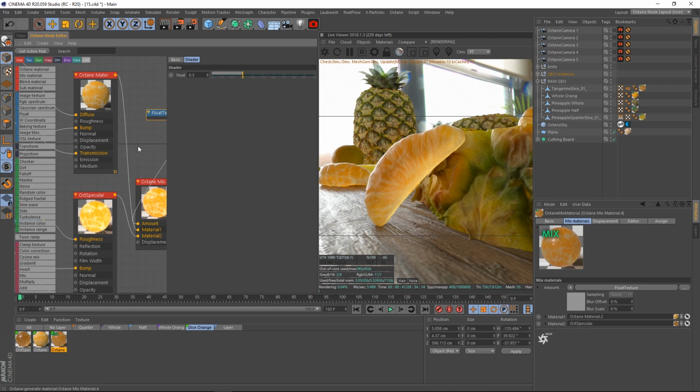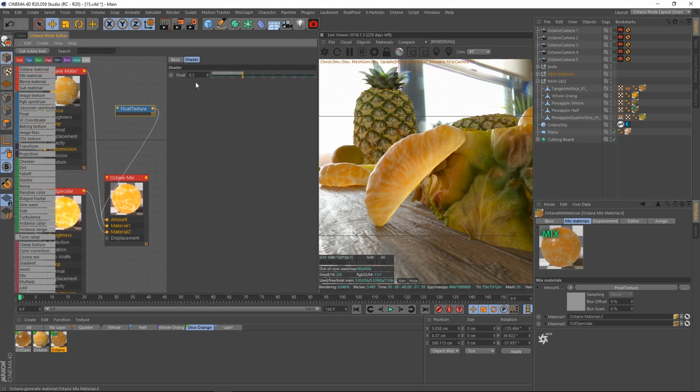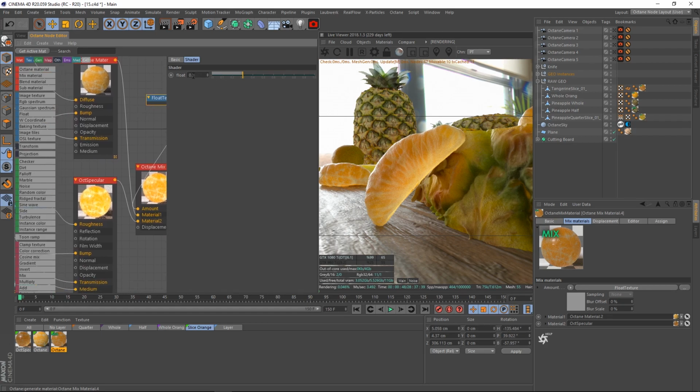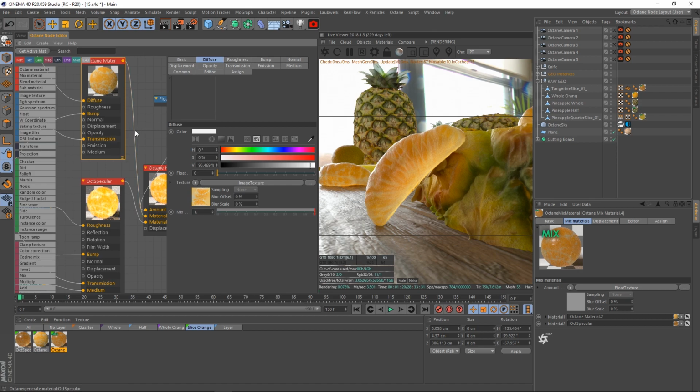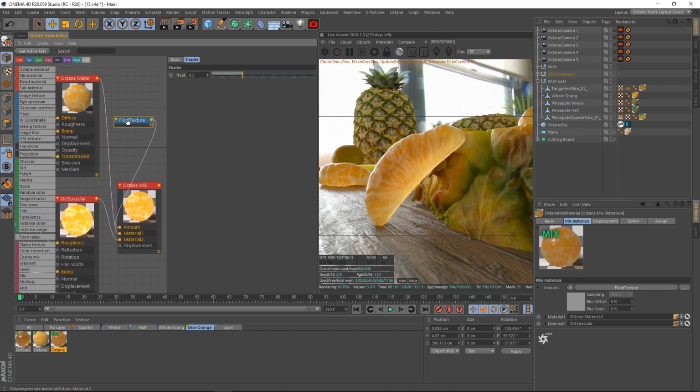And that was, again, by adding a little bit. We're only using a little bit of that diffuse. We're way over here only at 0.3. So technically, we're using 70% of the specular material and 30% of the diffuse material. So again, we're using just a little bit of it, but it really did help. You can see this is with the proper mixture, and this is with just the specular.